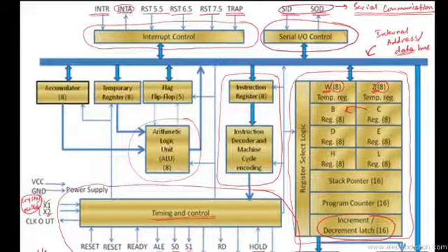The interrupt acknowledge pin is useful whenever we accept an interrupt. We make the 8085 accept an interrupt request through the INTR pin, so we can say that the INTR and INTA pins work in conjunction. We had discussed it in detail in the tutorial on interrupts, so you can refer to that if you need further information.